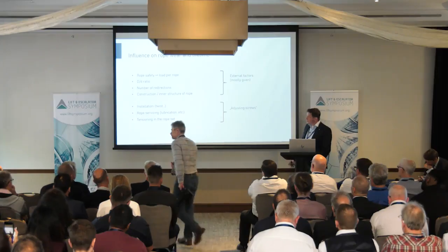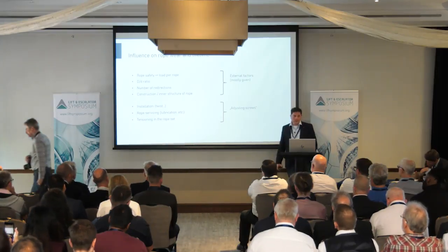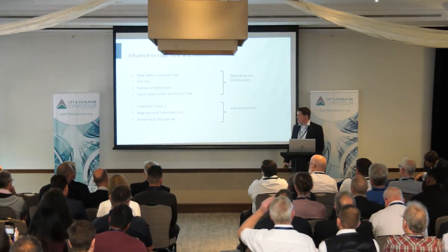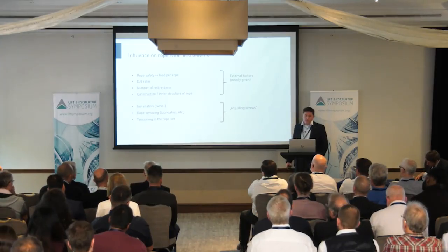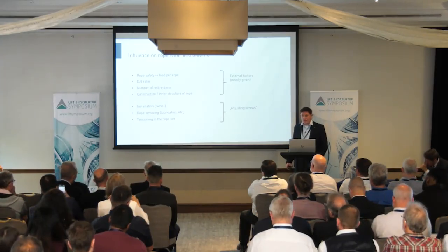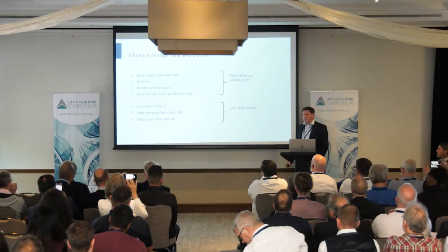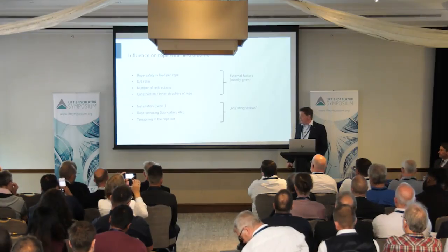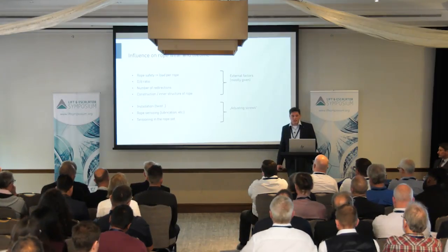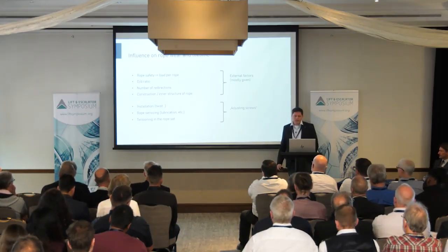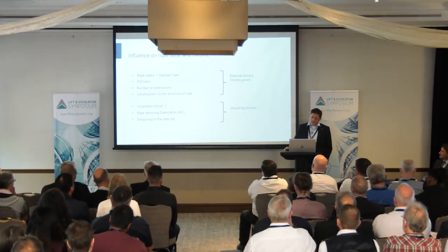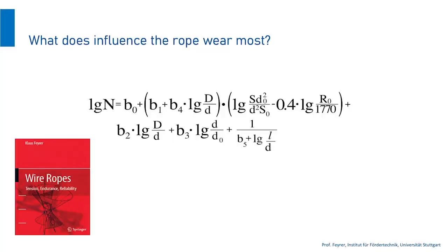Let's call them adjusting screws you have after the elevator is installed: the installation of the ropes, taking care about twisted ropes, things like that, rope servicing, lubrication, and the tensioning within the rope set. And this last point is really interesting and influences the rope wear for a huge portion.